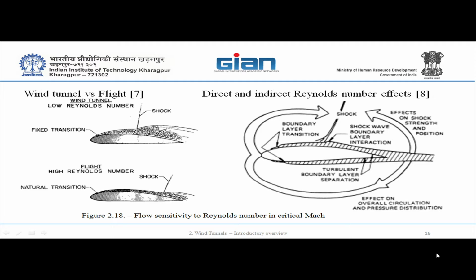And the meaning of displacement thickness is that your boundary layer actually swallows some of the volume of mass it should transfer. So the layers above have to accelerate, speeding up. Once they're speeding up, you get your Mach number 1 earlier, and you get a shock wave.